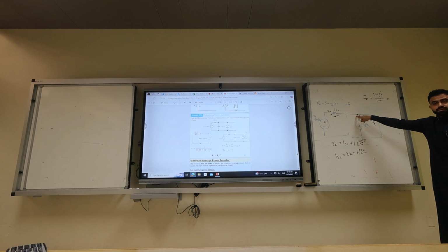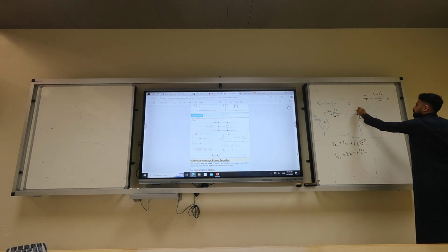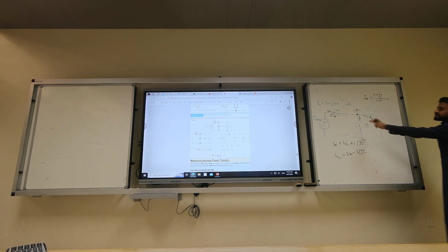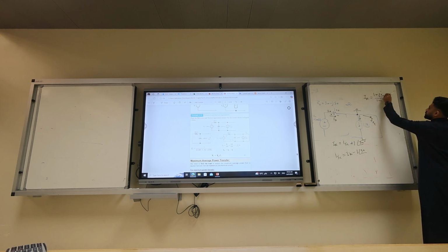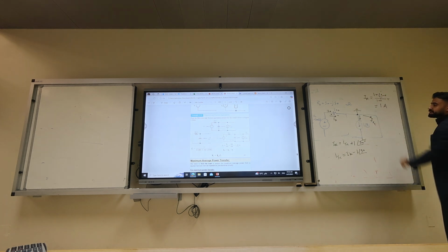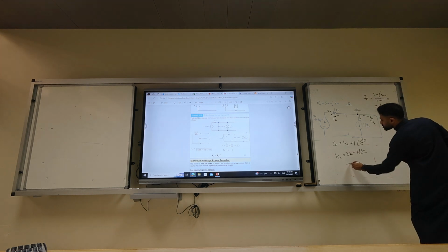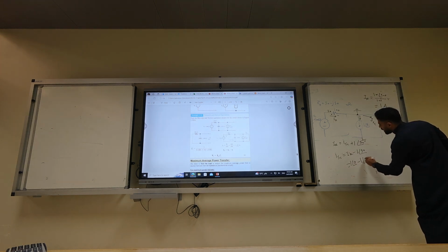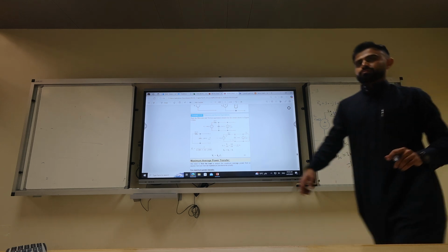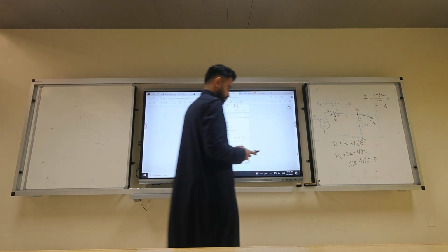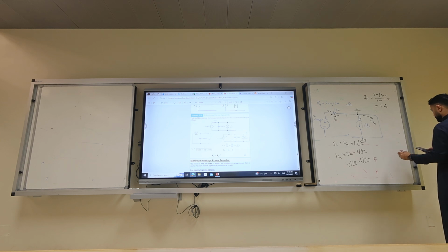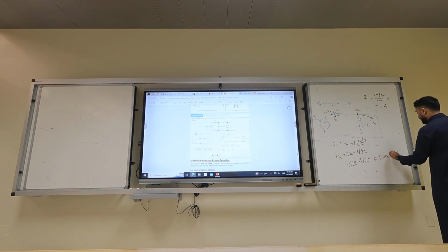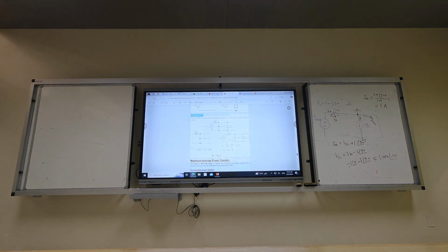Hatem, what's the voltage here? 0. Can I do it this way? So the current IR is V minus 0 over R, which is 1 amp, right? Yes. 1 angle 0. So 1 angle 0 minus 1 angle 90. What's the phasor? 1.414 angle minus 45, right? Correct? Yes.